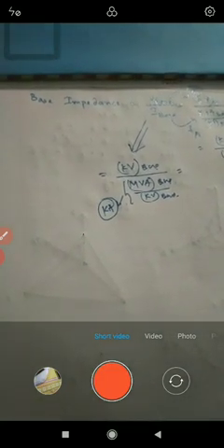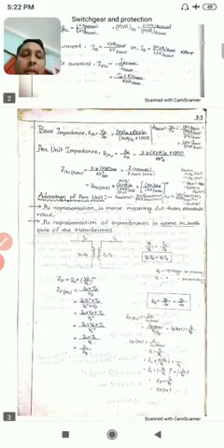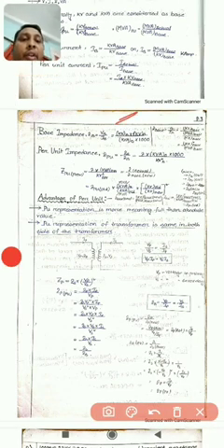Here it is. You can see both are given. This is using MVA. So both the options are there, and both are equal. So if you take now per unit impedance, what will be per unit impedance? Z actual by Z base. What is Z base? Z base, you can use this one or this one, either way.